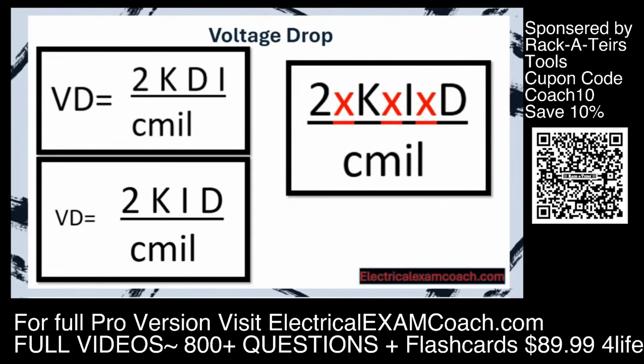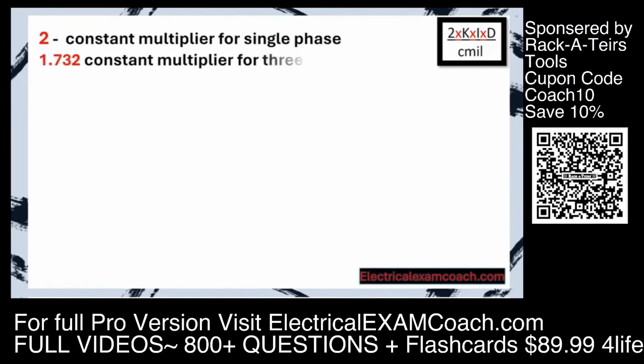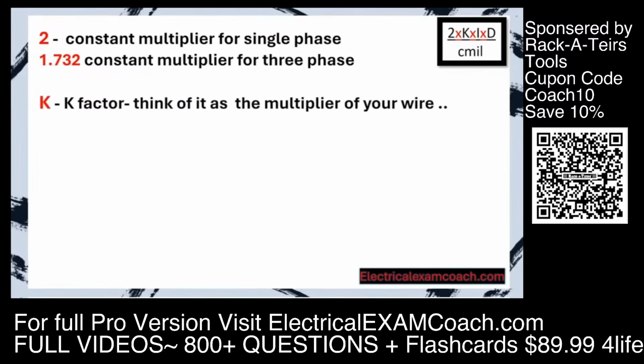Now let's learn what each one of these individual pieces mean. 2 is going to be our constant multiplier for single phase. If we're doing 3-phase, we're going to use 1.732 as our multiplier. K is going to be the K factor. And I want you to think of it like a multiplier for your wire. For copper, it's 12.9, and aluminum, it's 21.2.